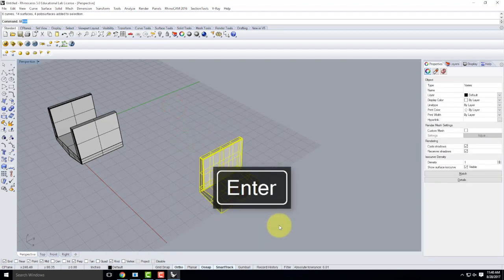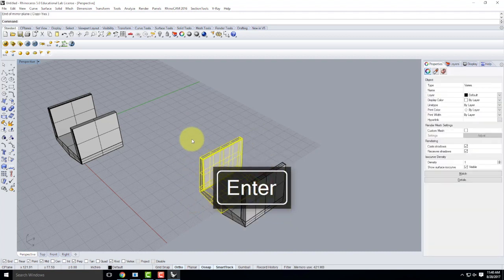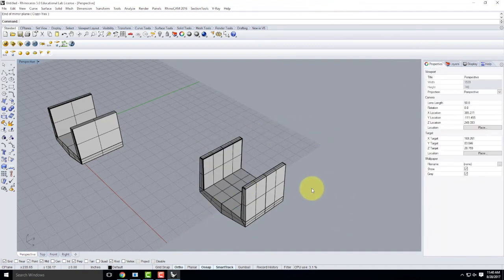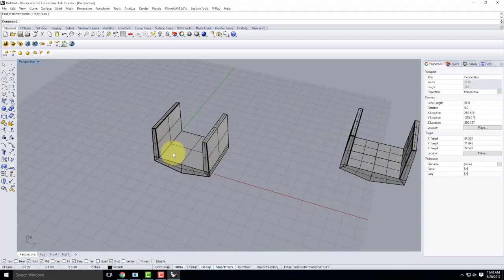I'd take these two and mirror it this way. So in terms of efficiency, I'm only doing that detail work one time, and I'm, by mirror, multiplying it out 4 times. So this is certainly the efficient way of doing it. But for your purposes and learning the process, doing it over and over again is not a bad thing. But I at least like to point out how, if you're smart about modeling objects, you can end up using one side, if it has repetition, using the mirror. So once I'm done, it is time to set this up.